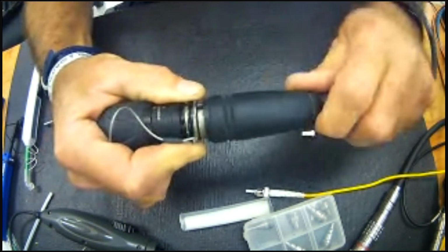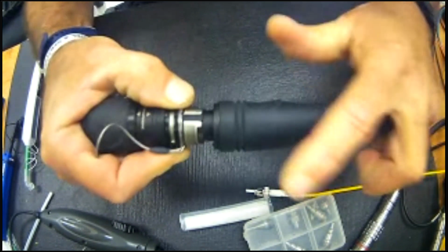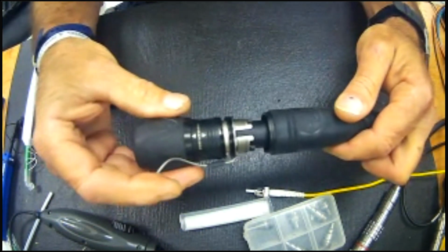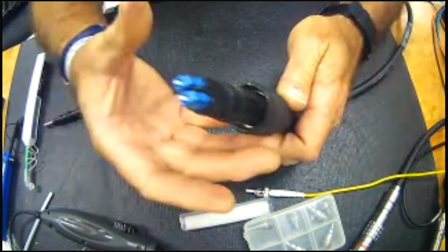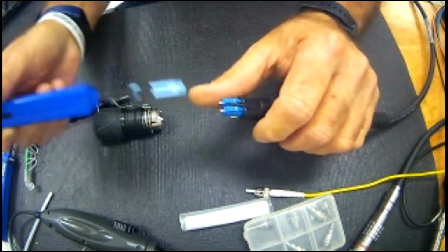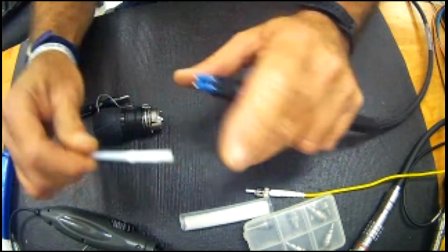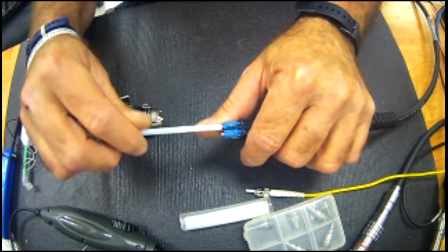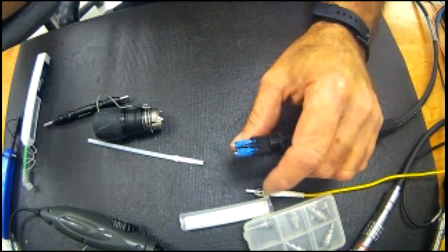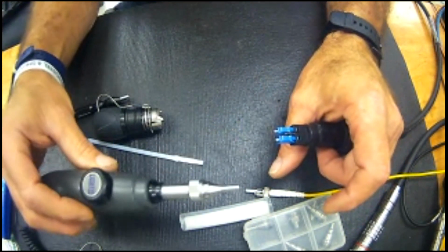So once you've unthreaded the back nut, after you've retracted that washer and that spring, if you keep the connector top dead center, that's where the name is, you simply pull the head off. Now you have access to two LC contacts. They're exposed contacts. You can go back to the one-click cleaner approach, snap, snap. You could use my universal I love you tool, reverse Q-tip, rub on it. Chem wipes, alcohol, anything to clean your tips. But most importantly is the ability to visually inspect them.